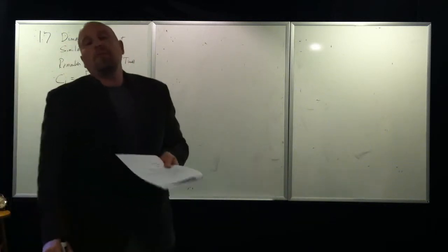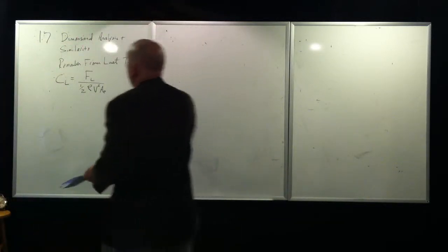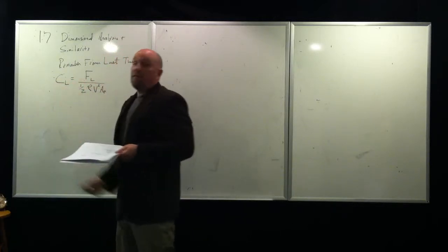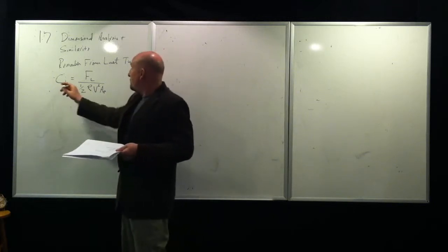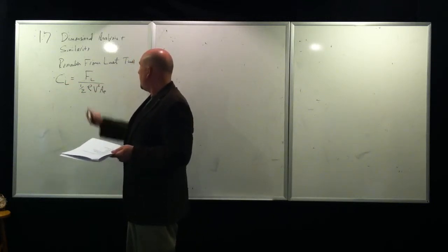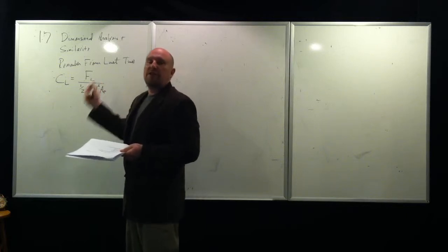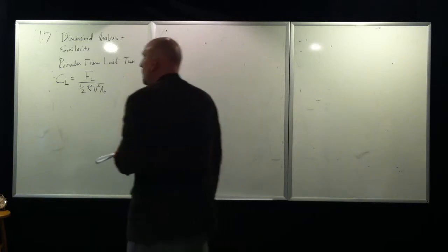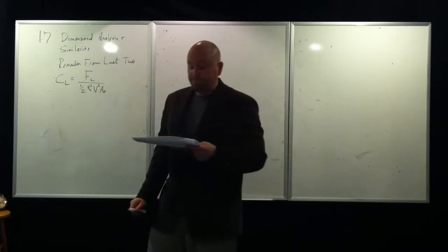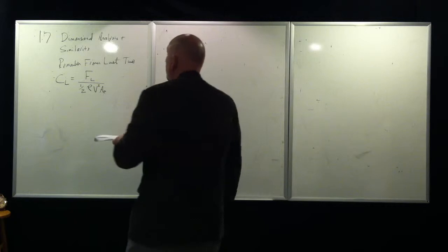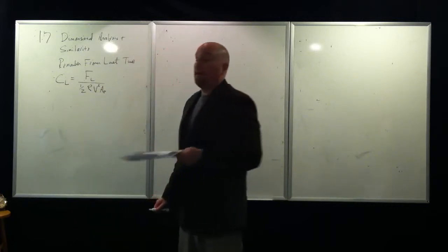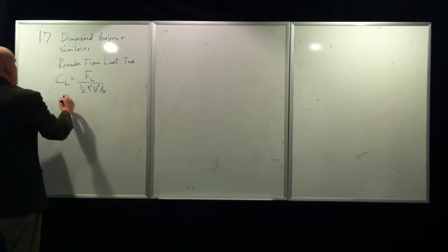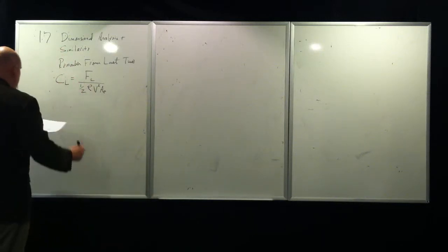From last time we had the formula for force of lift in terms of the coefficient of lift multiplied by this quantity. However, now we want to define the coefficient of lift as the force of lift divided by 1/2 rho v squared and the important area of your model as well as your prototype. This is going to be a result of dimensional analysis and similarity. So this will be the end result.